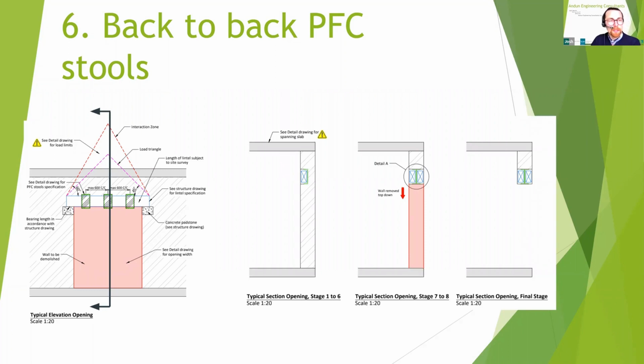This sequence is similar to the Pinyford stool method. However, this sequence allows multiple lintels to be installed side by side, which is often the case on thicker walls. One side is usually completed before the other to ensure that the wall receives as much support as possible throughout the works. So here's what we do. We break out the pockets and install the stools on one side only. So you only break out half the thickness of the wall, install the stools, and then dry pack those stools.